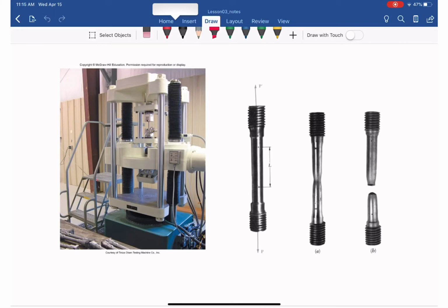As you can see, the necking happens here, at that finger. As you apply increasing stress, at a certain point it necks, and the size of the cross section of the specimen reduces. As it keeps increasing, at some point it will rupture, so the material no longer performs as intended.